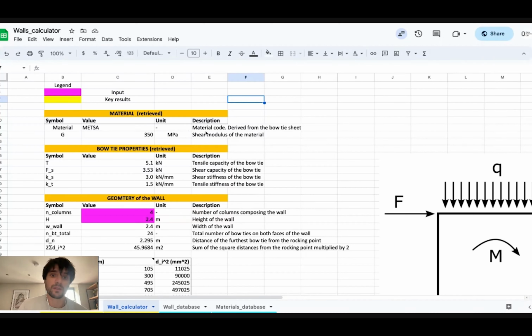If you use two different materials, you might induce the failure in one or the other. Whereas if you keep it the same, you know that the failure load you're estimating for the bow tie, for example in the case of failure of the contact surface, would be the same failure load for the surrounding panel, because the material and the contact surface will actually be the same.